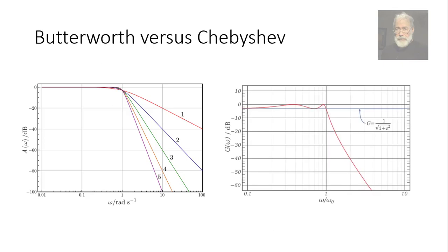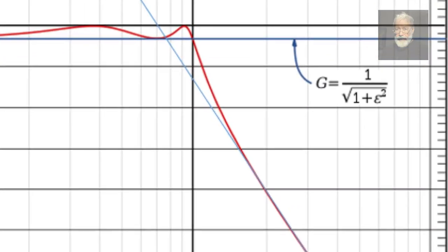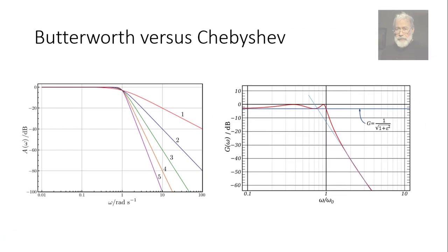For the corresponding Chebyshev filter, order 4 in this case, you see that the exit slope of the fourth order will be given by that line, whatever it is, but at the very beginning, right after the edge of the passband, the slope is steeper than the order of the filter, so it's steeper than the slope of a Butterworth filter. So that's why it decays faster. That is a characteristic of a Chebyshev filter. How it achieves that, well, we will cover that in a separate video, not in this series.